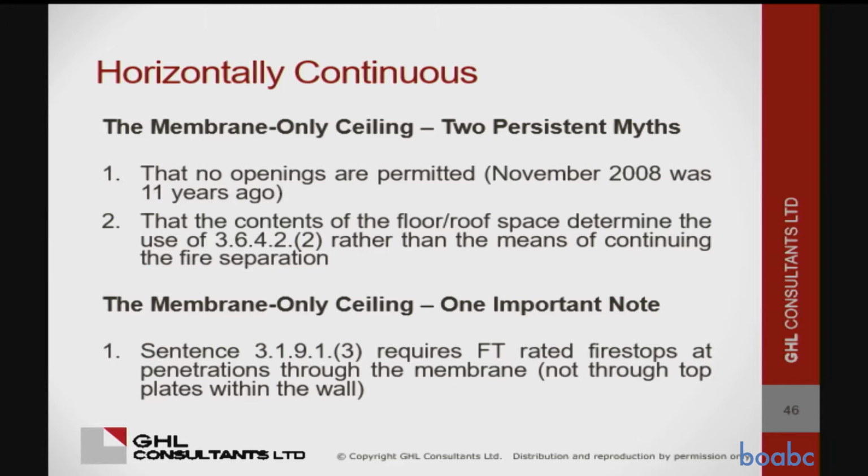And the one really important thing is that sentence 3.1.9.13 says that if you put a pipe or a wire through that ceiling, you have to have an FT rated fire stop. I mean, there aren't a lot of instances where you'd have a pipe in the middle of the ceiling, except maybe in the bathroom.